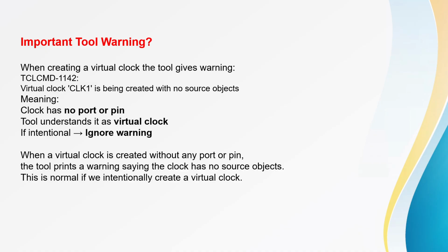When we are creating the virtual clock, the tool will give a warning. The warning is TCLCMD-1142, in Tempus Cadence. It says virtual clock clock1 is being created with no source object.